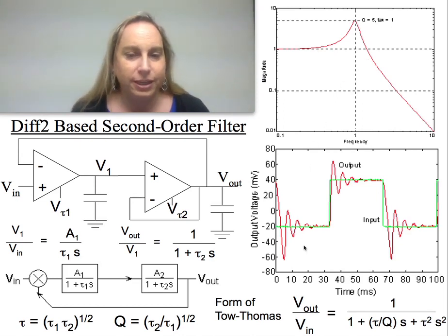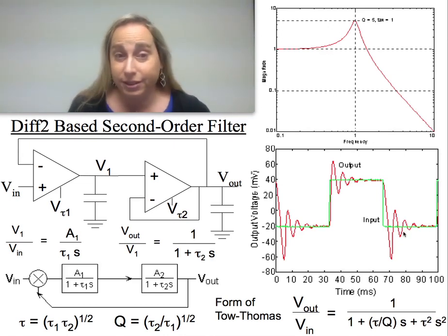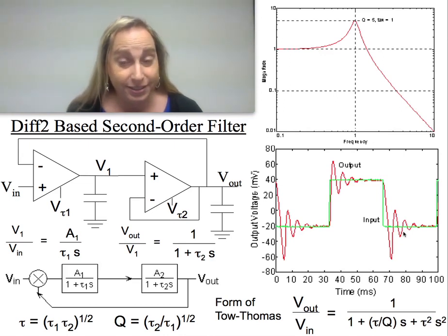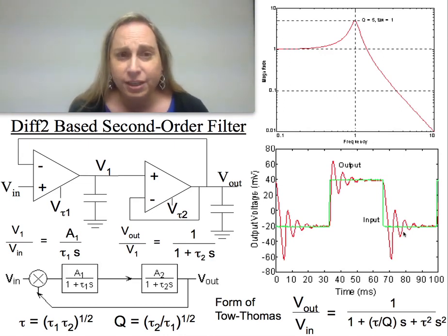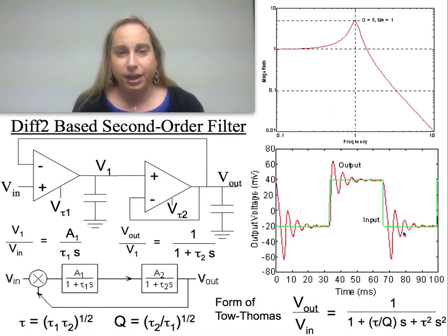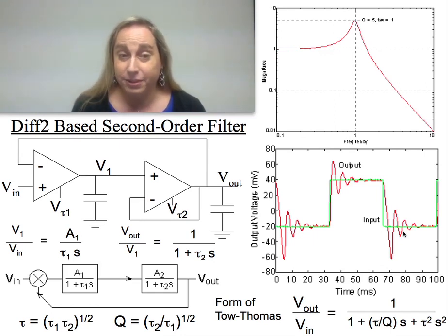Now, I typically like looking at the step response for a case like this, and this would be a similar case. It turns out to be a relatively similar Q, with a slightly different frequency corner. You put in a step response, a typical good way to look at this. I think most people would prefer to look at frequency response because that's what we're trained on as analog designers. On the other hand, there is a lot of information to be gleaned from the step response, and we shouldn't ignore that as we're putting it together.